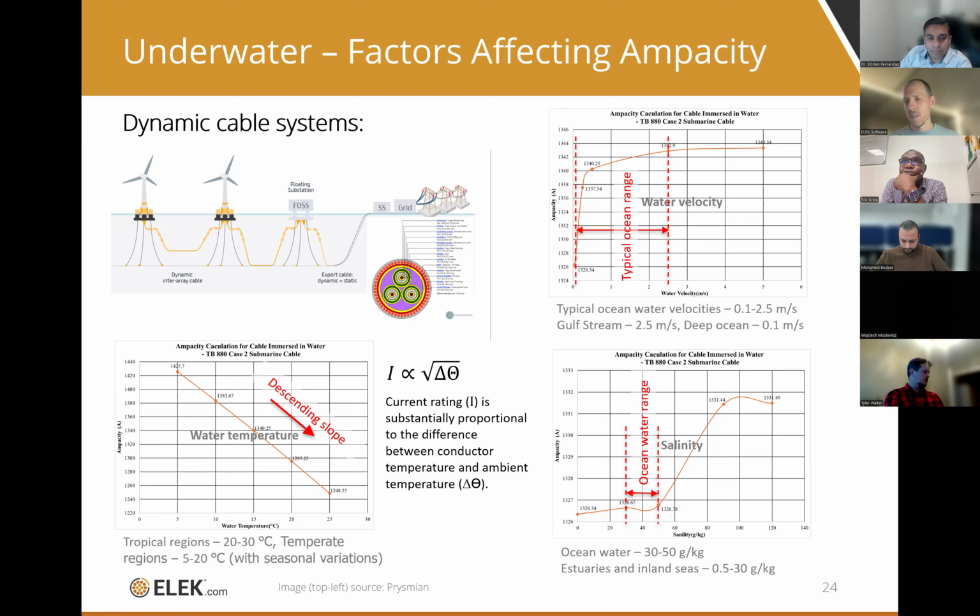We do consider salinity, whether the cables are installed in fresh water or salt water, highly saline water. It only really has a significant effect on the current rating if the water is highly saline.